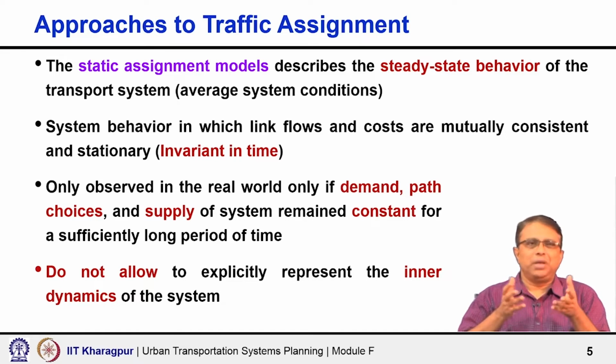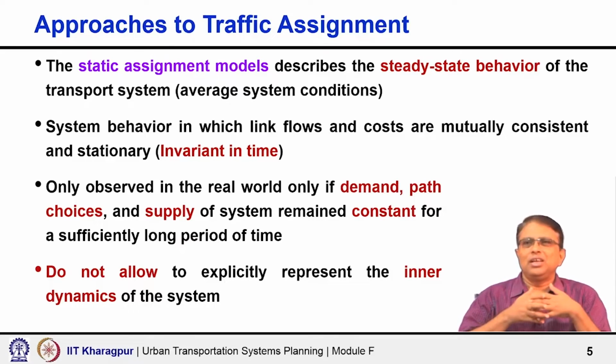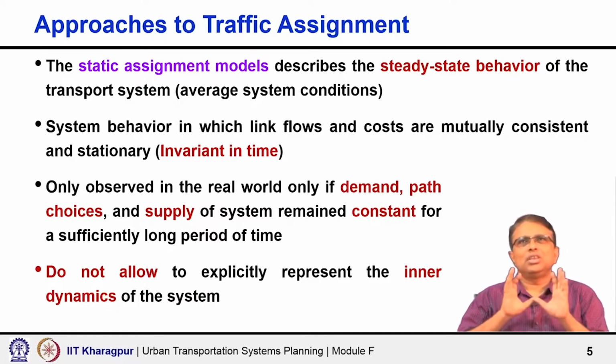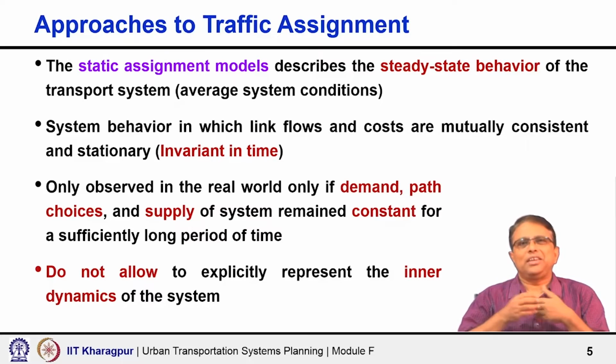Grossly, if I am doing planning, I want to know generally that the total traffic demand is this much and maybe the peak hour will be 8% or 10% of the daily demand, and that will be my design hour traffic typically for planning purposes. And if that is the traffic, then how the distribution will generally happen in the peak hour, or how it will look, it can tell me.